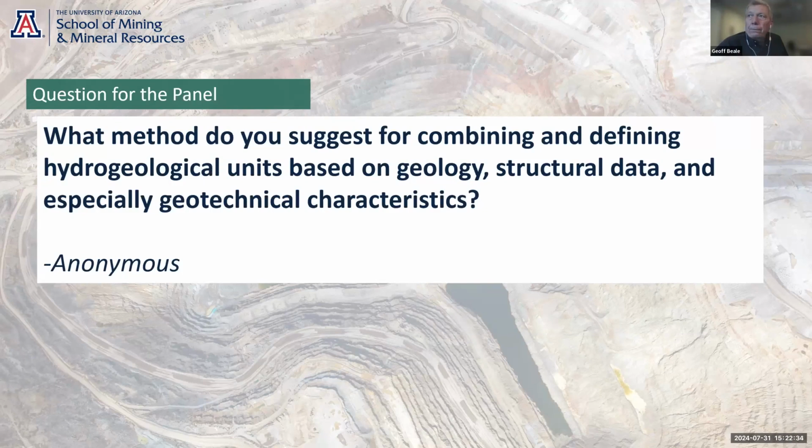So in terms of geotechnical differences, that really comes down to the smaller scale. You would look at the basic fracture frequency information, fracture frequency, RMR, to look at how that may differ. But really, again, it comes down to lithology, alteration, and possibly mineralization.